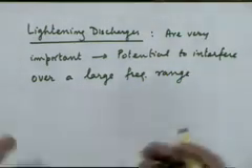Actually, the spectral characteristics of these discharges, this noise source, is not exactly a constant, because although we are saying it is an impulse, actually it is a pulse of some finite duration. The duration may be very small, but it's still finite. And what is the spectrum of a pulse of any duration? What is the nature of the spectrum? Same function, sin x by x.